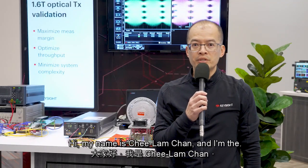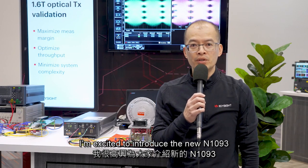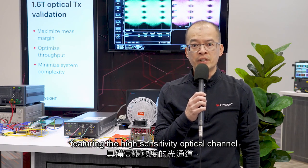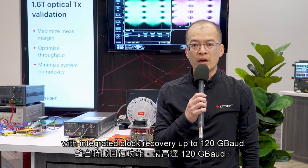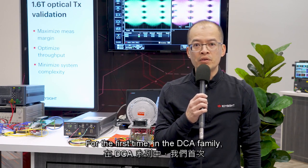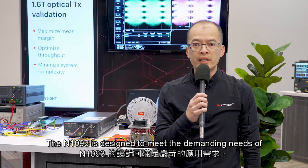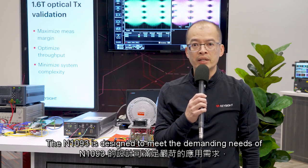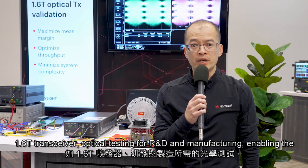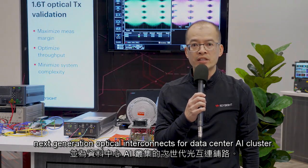Hi, my name is Chi Lam Chen, and I'm the product manager for Sampling Oscilloscope. I'm excited to introduce the new N1093 DCA-M sampling oscilloscope, featuring the high sensitivity optical channel with integrated clock recovery up to 120 gigabaud. For the first time in the DCA family, we have integrated the precision time base to achieve 90 femtosecond jitter. The N1093 is designed to meet the demanding needs of 1.6T transceiver optical testing for R&D and manufacturing, enabling the next generation optical interconnects for data center AI cluster.